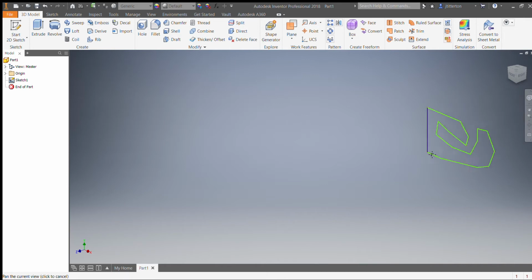Now, I'm using the roller button to zoom in and zoom out. Very handy. Up here is the little home button above the view cube. I was taught how to use the view cube, and you can click on it and play with it and click on these commands on the mini toolbar on the right. But I do everything with the mouse. It's a lot easier.